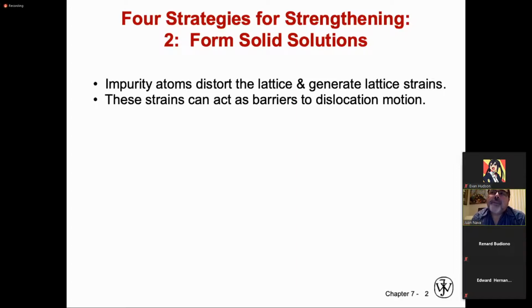Remember, you have two types of phase, actually three types of phase diagrams. You have the phase diagram corresponding to interstitial atoms. You have the phase diagram corresponding to an isomorphous alloy. In an isomorphous alloy, you are obeying the 4 rules for full miscibility. And remember that the isomorphous phase diagram has the shape of a cat's eye, telling you that in the solid state, you form a complete solubility of one atom in the other.